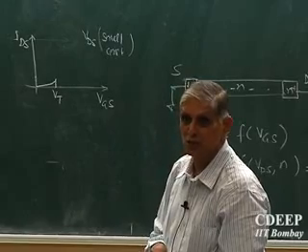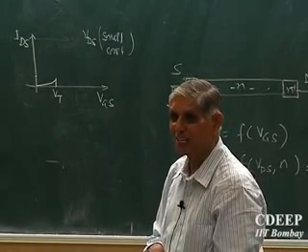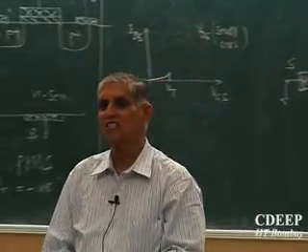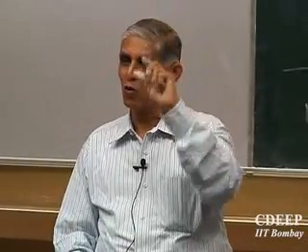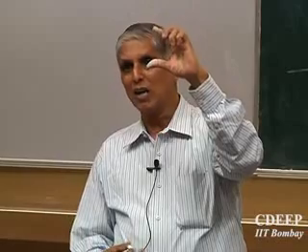We have said that at VT inversion occurs. No, it doesn't occur at VT. What was the condition of inversion I said in the capacitor? When psi S crosses, Ei crosses EF, inversion sets in. But what is the definition for VT I gave? 2 phi F. So from phi F to 2 phi F, the inversion layer, though the number of carriers is smaller, exists. This region is called the sub-threshold region. Is that correct? Sub-threshold currents are not zero. They exist there. Is that clear, ma'am? From psi S equal to phi F to 2 phi F, we are not declaring VT, but inversion has already set in there. So this is called sub-threshold current.